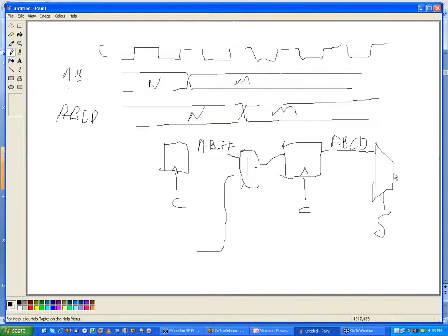There's S. There's O. So it could be that our S, and the reason maybe we had these flip-flops, this is just an example, maybe S is not valid until this time. Okay, so maybe it's not valid, and we knew that this was going to change here, so we know that the sum is going to occur on this clock, and so we aligned our S. There was kind of like a race condition.